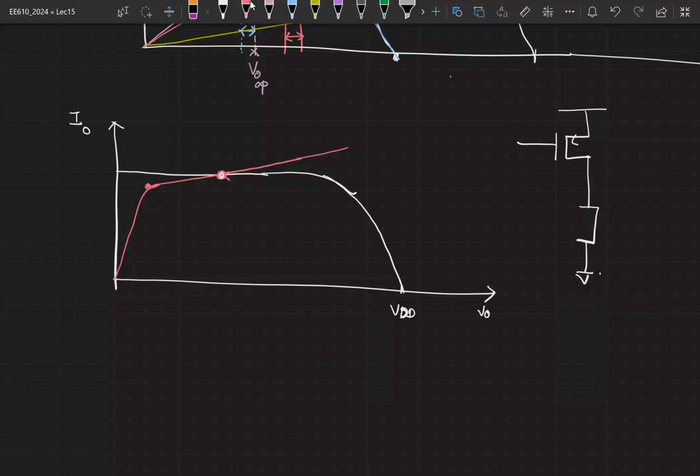So if I put an NMOS transistor here, right, and so this was at some bias voltage, plus you had an incremental voltage here. This is connected to some bias voltage, no incremental voltage riding on it, and I pick up the output from here. This is some V0 plus Vi, right? Then that basically corresponds to the I0 versus V0 curve I have plotted here, right?